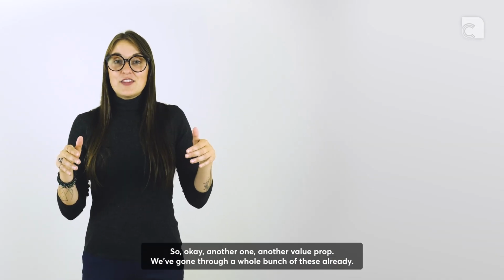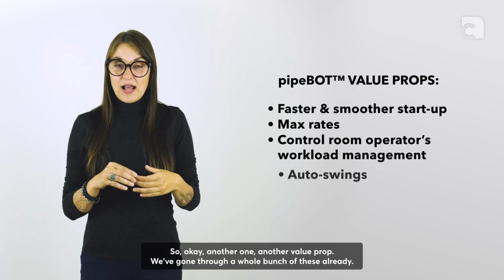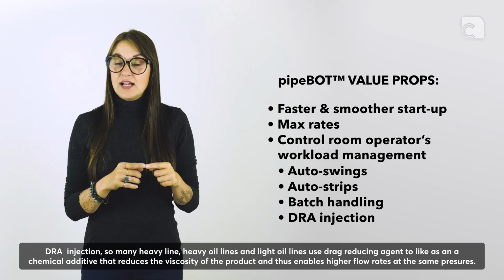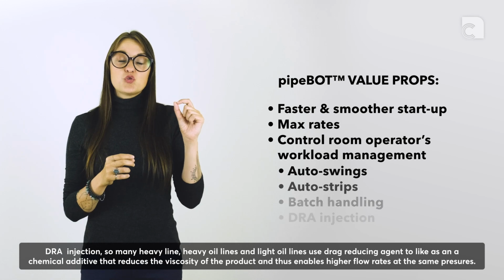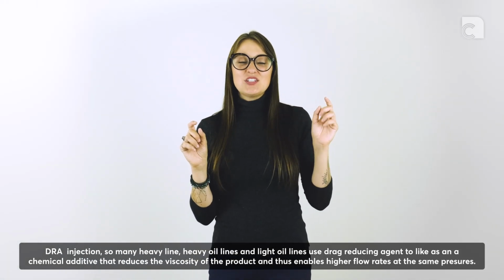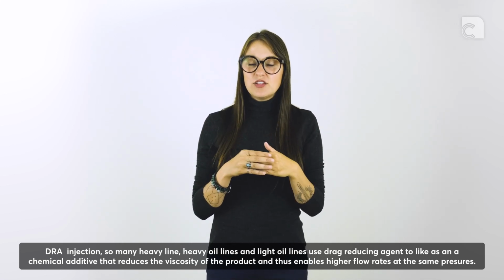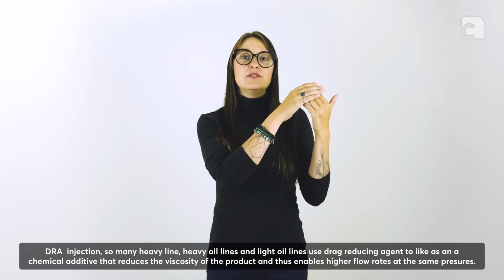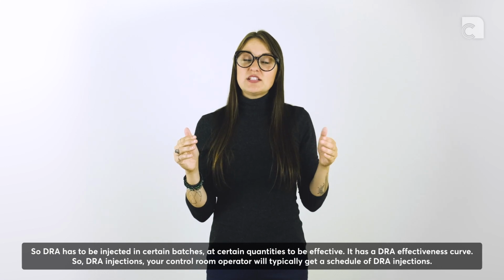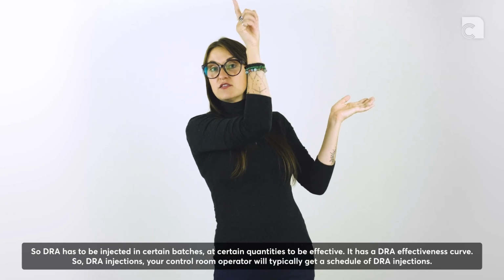So, okay, another one, another value prop. We've gone through a whole bunch of these already. DRA injection. So many heavy oil lines and light oil lines use drag reducing agent as a chemical additive that reduces the viscosity of the product and thus enables higher flow rates at the same pressures. So DRA has to be injected in certain batches at certain quantities to be effective. It has a DRA effectiveness curve.